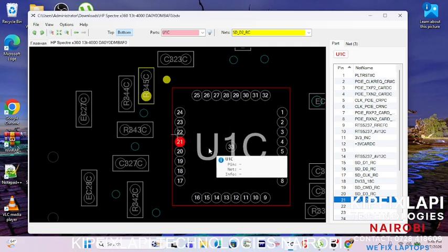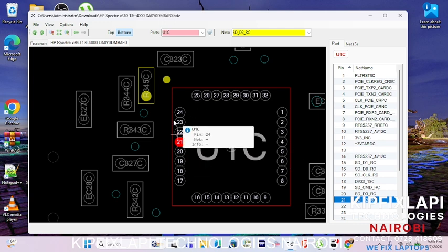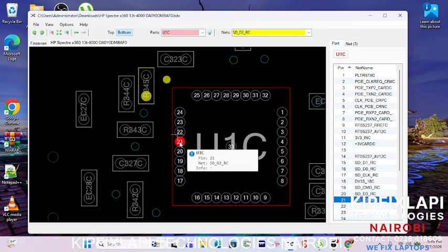This Boardview file is important when you want to find out, let's say this IC was corroded and we have some missing tracks here. When you have missing tracks and you're not able to find exactly where that track was connecting to, it is always good to use the Boardview files, because you'll be able to select a certain pin, for example, this one.